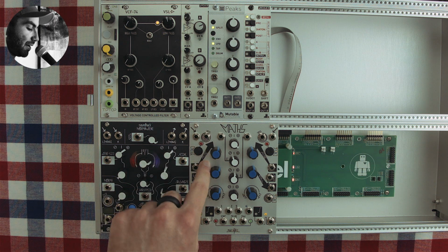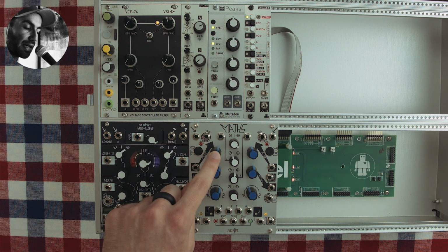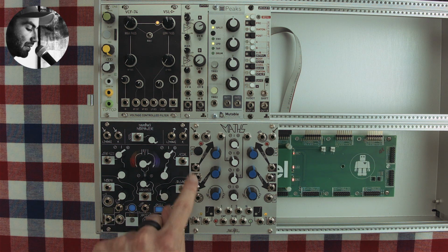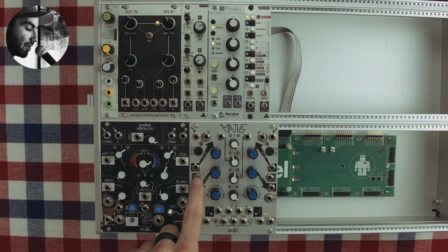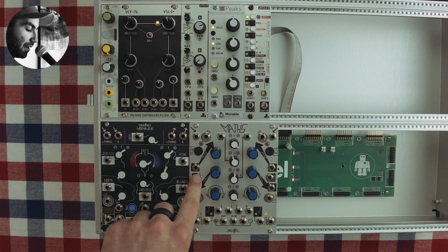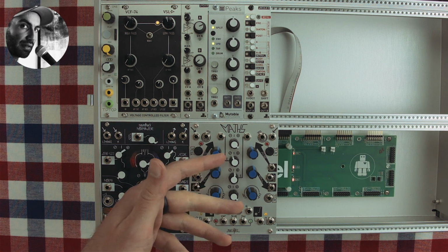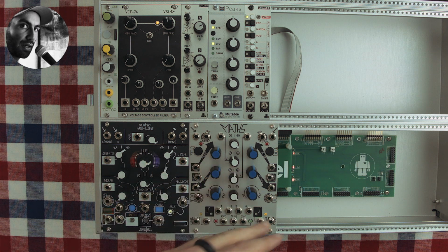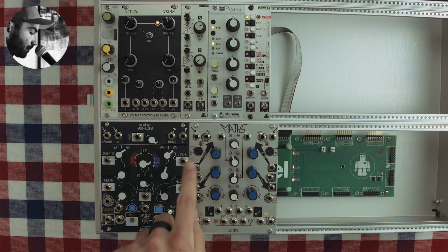Moving down below, we have these 2 knobs for controlling the rise time and the fall time. Each one has its own independent CV control. There's also this both CV control, which will control the entire function, but this one behaves in an opposite way, so high voltages will reduce the time effectively.